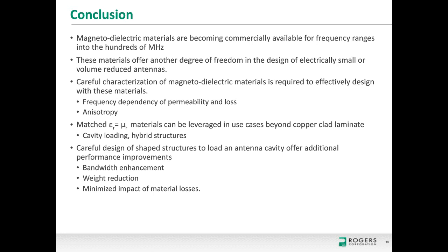Next question, how much power can the material handle? It'll really depend on the antenna design, or another way of thinking of it is how concentrated the magnetic field is. The material, all magnetic materials will have a saturation magnetization above which your permeability is effectively 1. So it's tough to answer without a specific example.